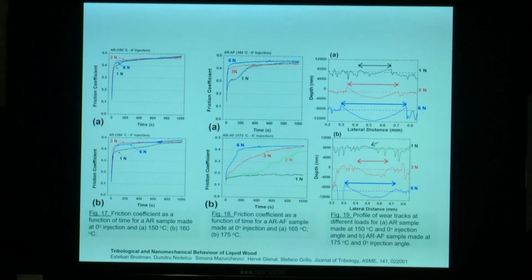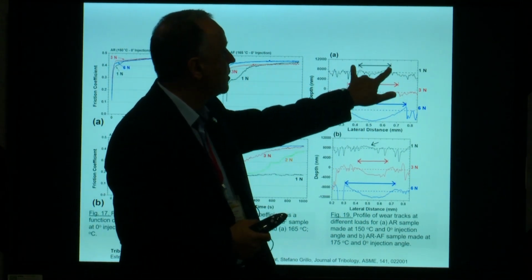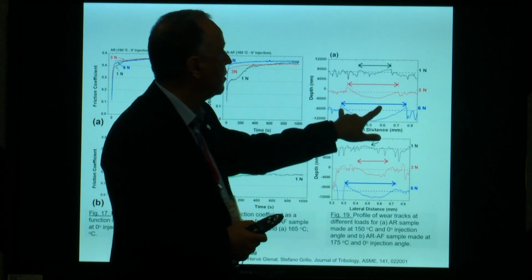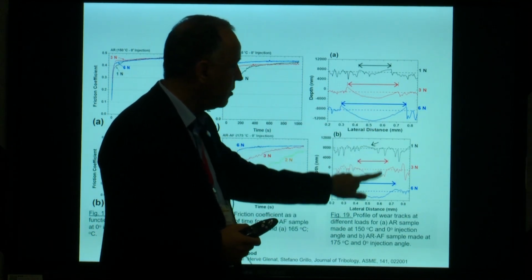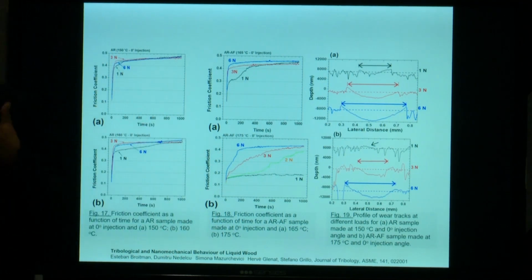Concerning the wear tracks, the results were as we expected. The wear tracks increase with the loading force. You can see loading force 1 Newton, this is the wear track, 3 Newton and 6 Newton. So also for our material, the wear tracks were the same, increasing with the loading forces.